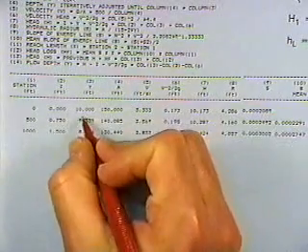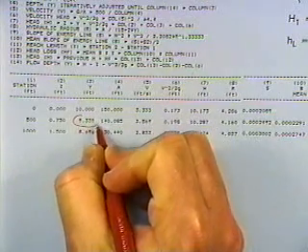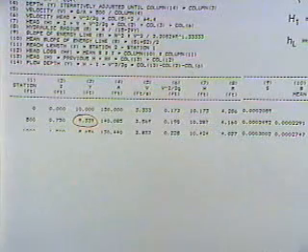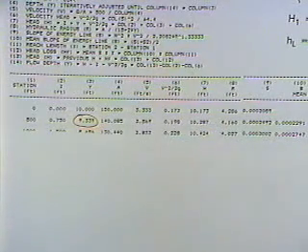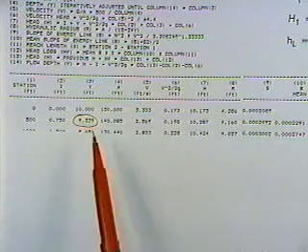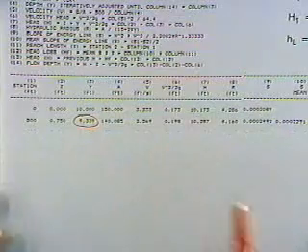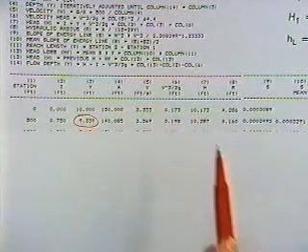I don't know the depth. And so what I'll do, I've got to assume a number right here in your table. That's the number I don't know. And I know it's something less than 10 feet. As you go up the concrete channel, the depth decreases. And so I make a guess. And after I make a guess of the depth, then I can compute everything.